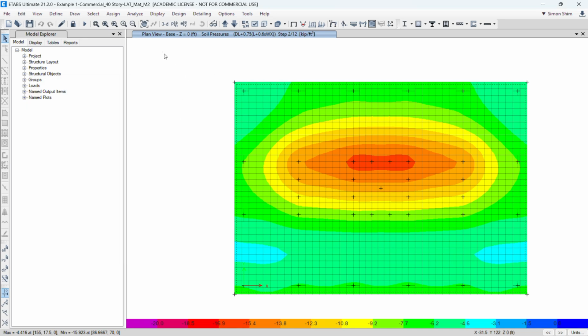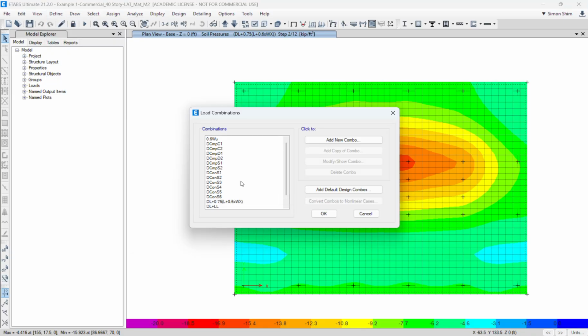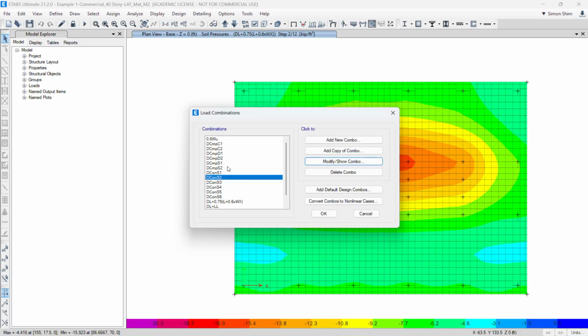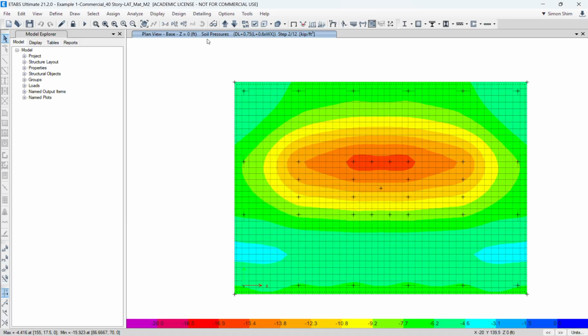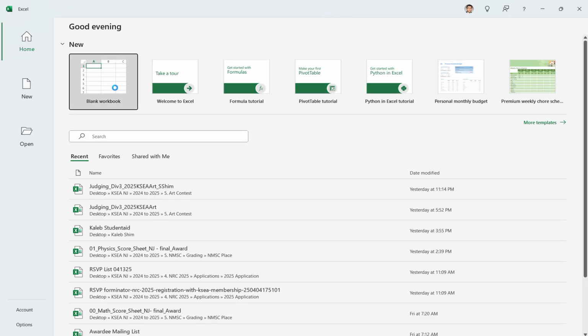All right, so next we'll spot check our shear stress. Let's see, what do we have? Okay, so here this is an ultimate load combination, S1 to S6. S2 is 1.2 dead, 1.6 live load. Okay, so this is the ultimate load combination. We have to check all the shear stress. Now in terms of shear, you should be aware of what the concrete shear is.